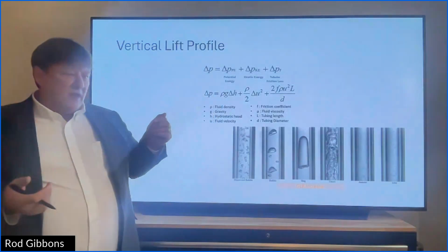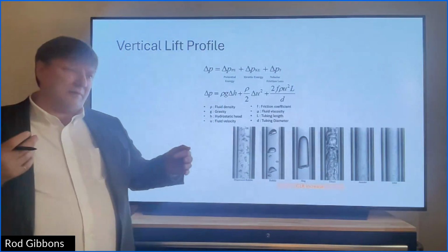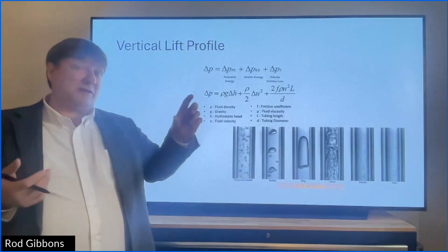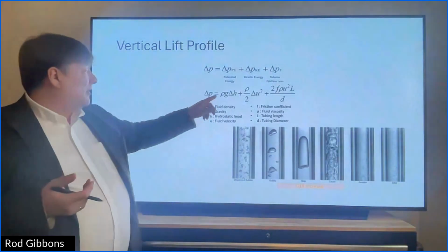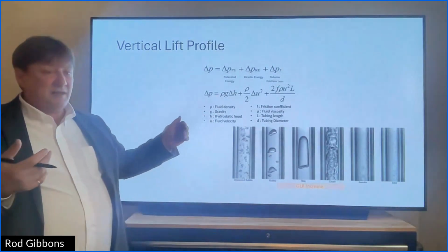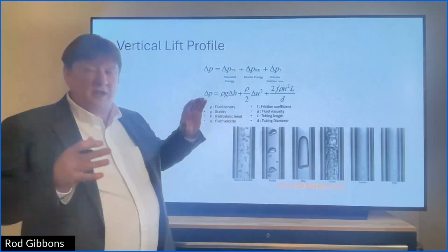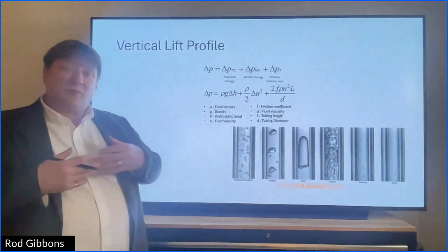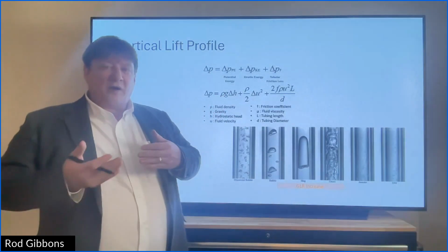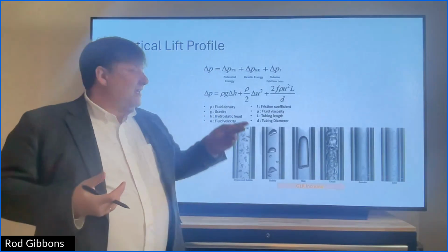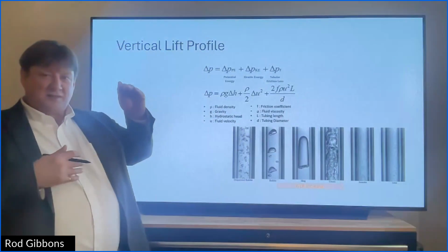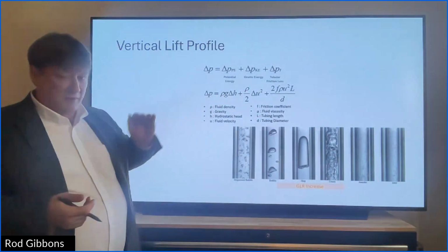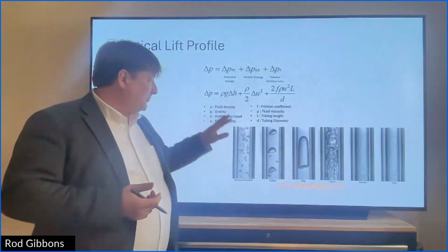And so you can have gas, which is much less dense, but water is say 20% more dense than oil. Usually, again, depends on the oil type. But when the fluid changes, if you're water flooding, if you've got water pressure support, if you start to get water cut, this is going to change this hydrostatic pressure. So that's always a good formula to know, either in production or in well control.